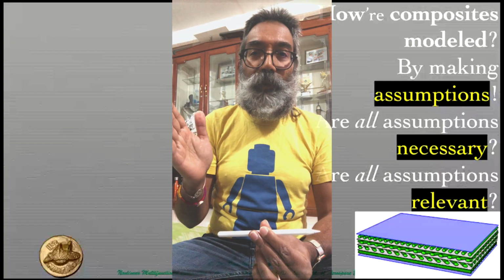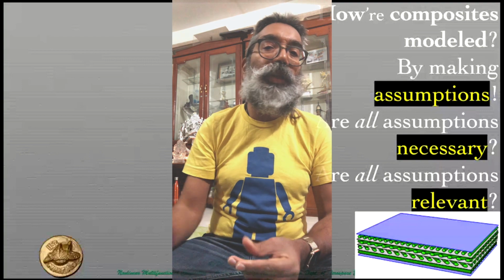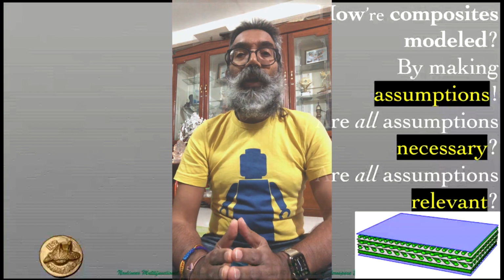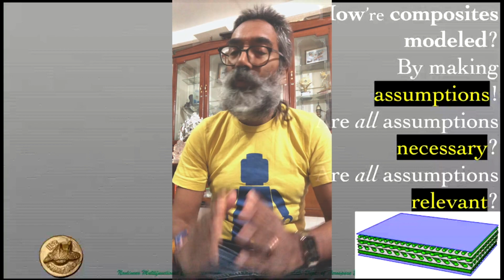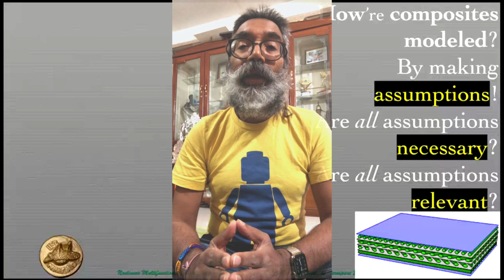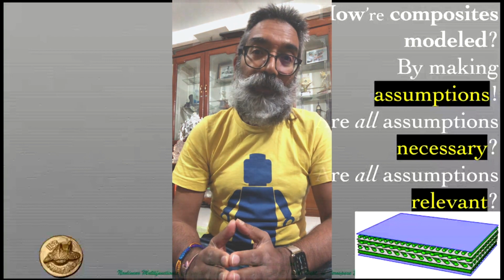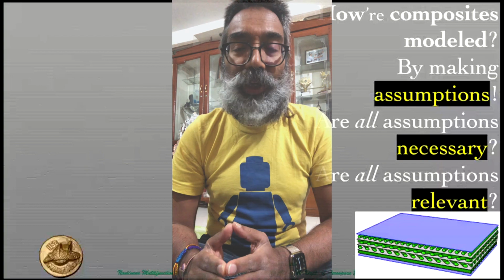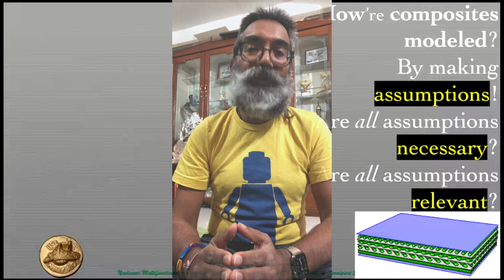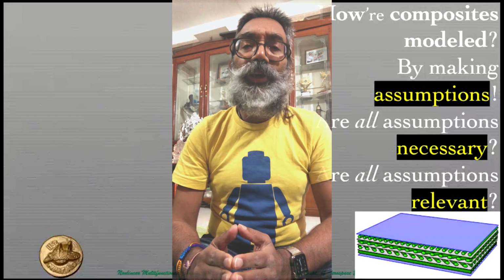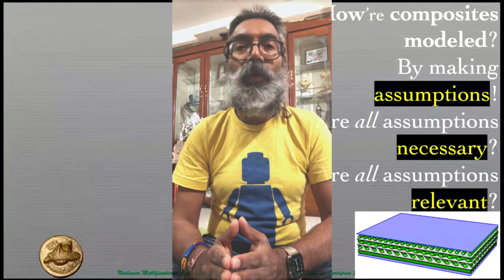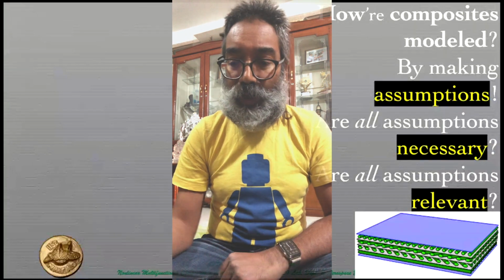And so aging is something that is involved with that. But another important thing that you would see is in terms of other kinds of loading, like thermal loading and thermal fatigue, and that can result in creep or permanent deformation. So how much permanent deformation are you willing to live with? So the property reduction on the one hand and the permanent deformations that might result, whether you go for very high temperatures or you go for the fatigue mechanical loading where there's a property reduction.